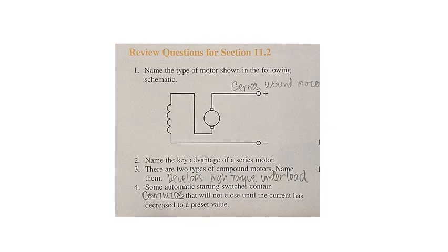A key advantage of the series motor is its ability to develop a high torque under load. Under load conditions, the armature speed is low and the CEMF is low. This condition results in a high armature current and increased torque. Series motors have heavy armature windings to carry these high currents. As the motor increases in speed, the CEMF builds up, the line current decreases, and the torque decreases. Series motors are used on electric trains, cranes, and hoists, as well as other traction type equipment.